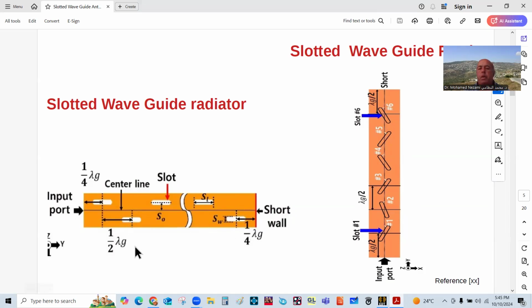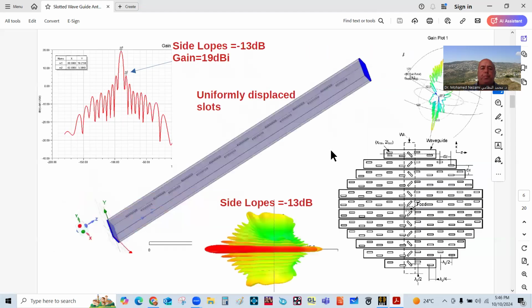Previously, I went through the model of this as a transmission line where these slots are basically parallel loads. That's why at a quarter wavelength you need an open. At the end, you need an electrical open, which is physically short, but it's really a quarter wavelength from the center of the slot. The other ones in here, the feeder ones for the stacked waveguides, are basically in series, and that's why you see an actual physical lambda over 2.